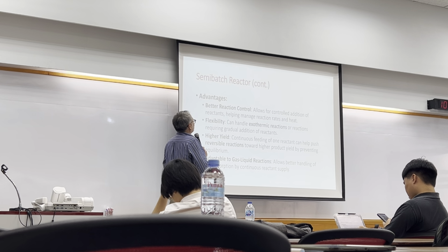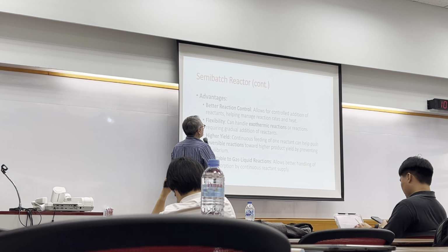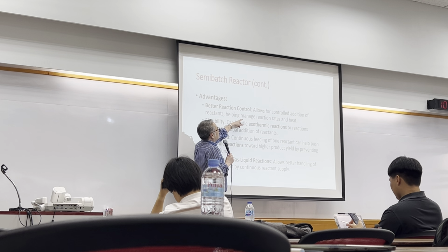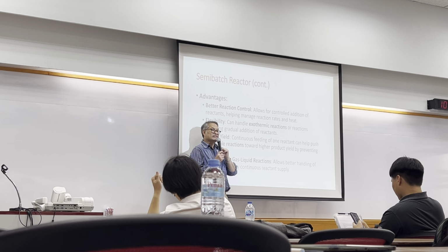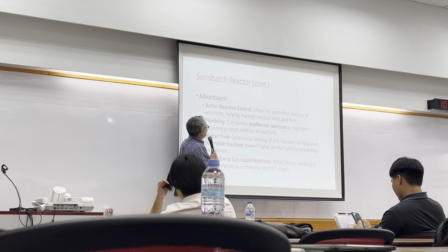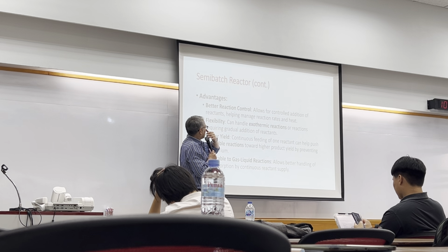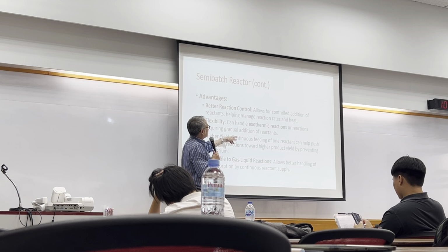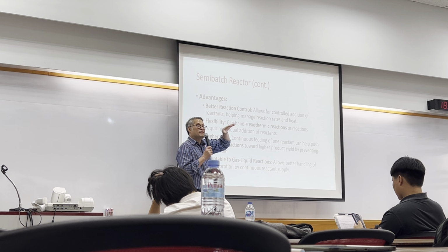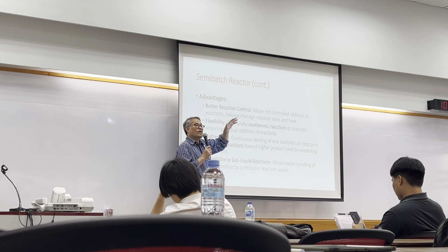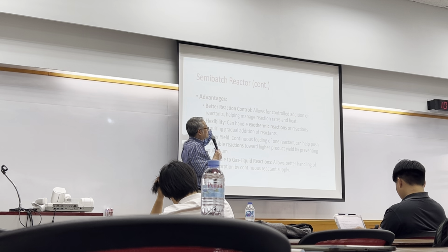Advantage of semi-batch: better reaction control, because we can control how much reaction proceeds by controlling the addition of the reactant. Flexibility: it can handle exothermic reactions or reactions that happen at the same time, which we call parallel reactions.